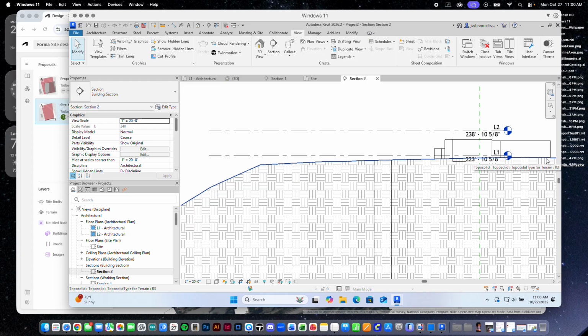Okay, so what we'll do is we'll be going back and forth between sort of, it's almost like having the grid paper underneath as a base underlay for your trace, right? Here we can always go back to it. And if we build off of it, we can always go back and change the underlay, and everything will move with it. Right? So the structural engineer comes back and she says, well, I know you say 30 feet spacing center to center between your steel columns, but it's really more like 28 feet and 6 inches. You go, no problem. You go back to your grid and just change it. And then everything updates, right? So that's what we'll do.